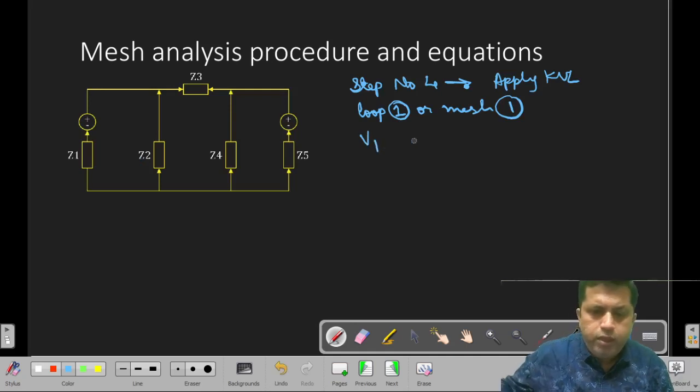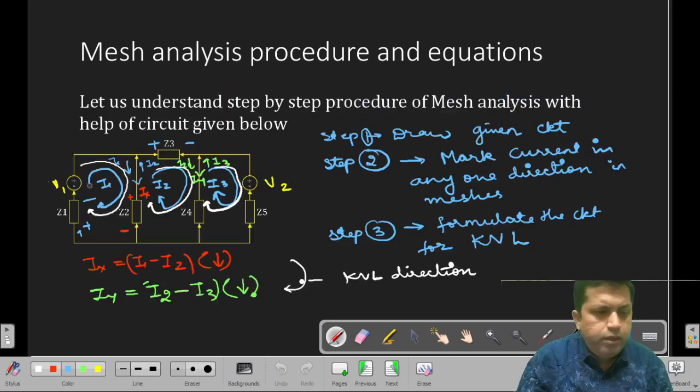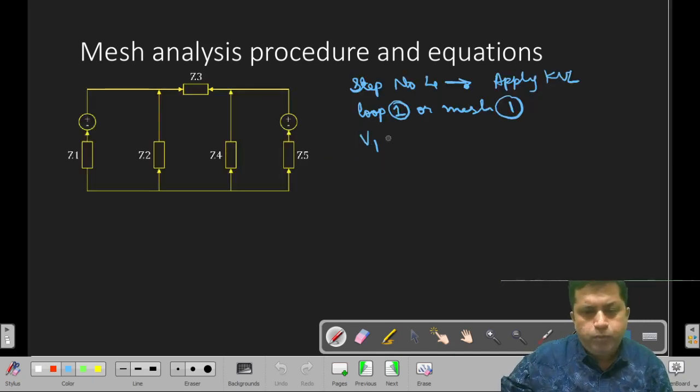And then second is impedance Z2. So we are going clockwise from V1 to impedance Z2. For Z2 the voltage drop is plus to minus, that is a drop. What is the voltage drop? Ix into Z2. So plus to minus is minus. Current through Z2 is Ix and impedance is Z2.